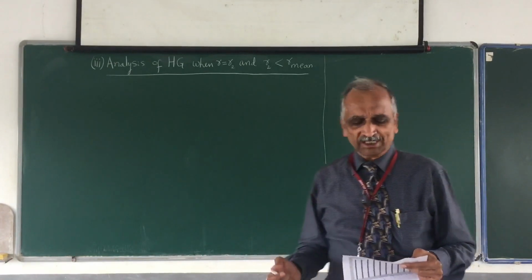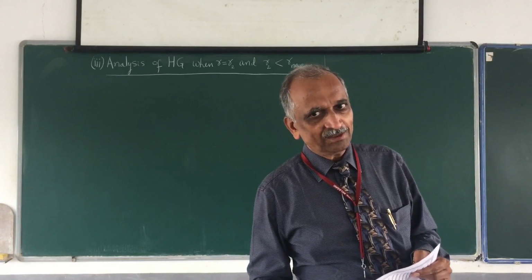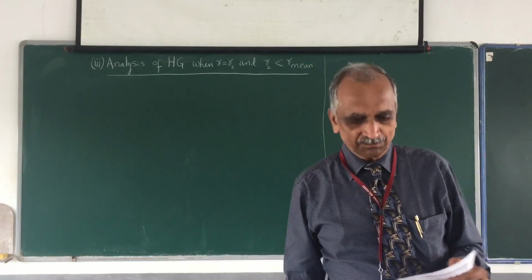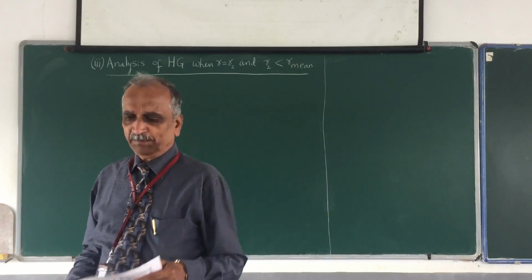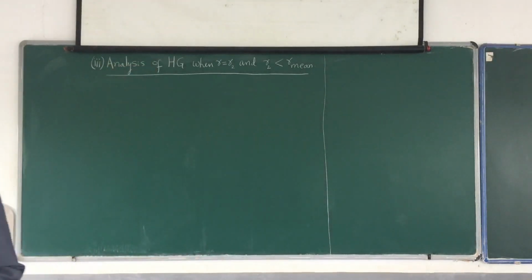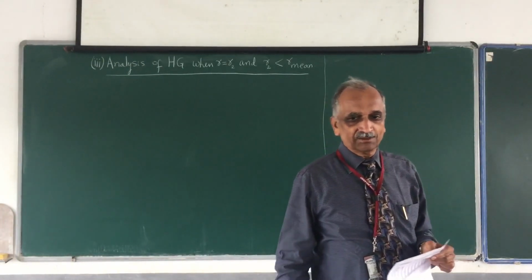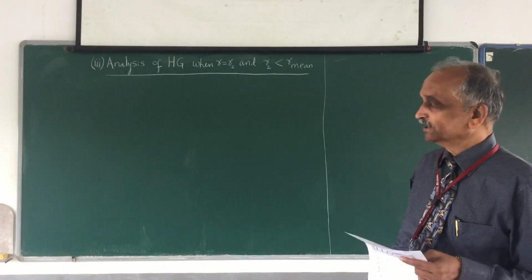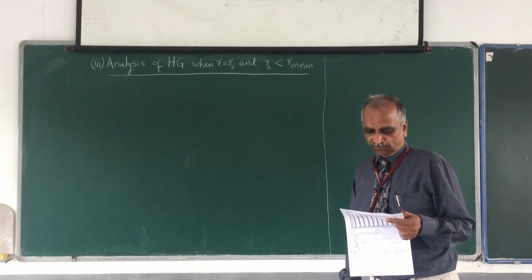Mass of each ball as MB, mass of the sleeve as MS, then A is the length of the sleeve arm of the bell crank lever. Then B is the length of the ball arm of the bell crank lever, and C is the distance between the fulcrum and the axis of rotation of the spindle. And then K is the stiffness.